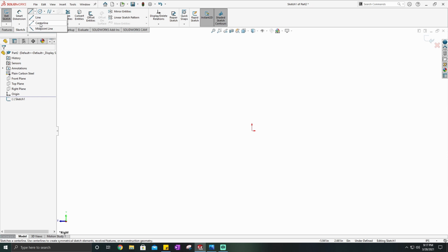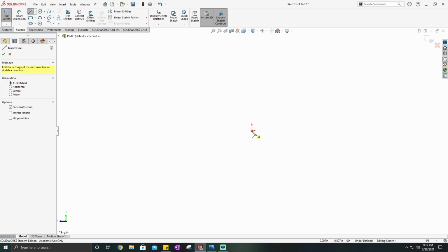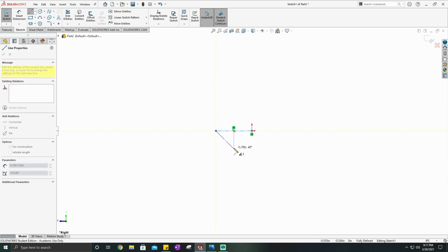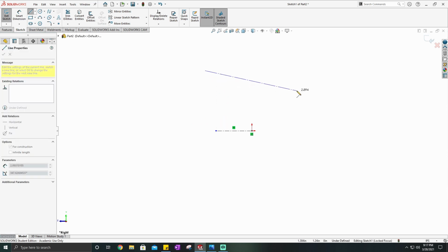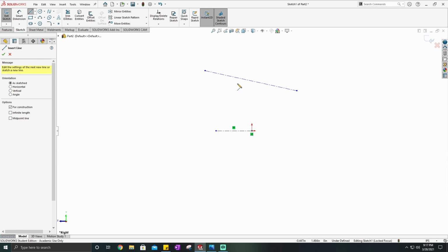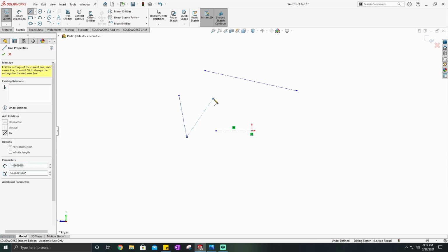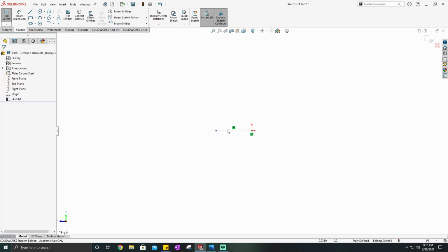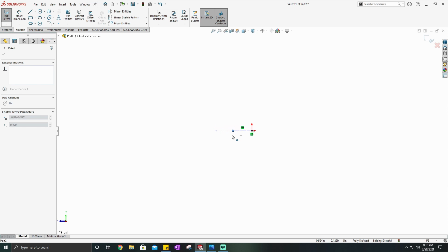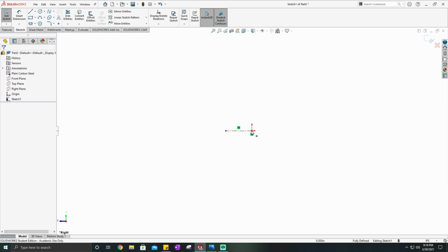The first thing to do is start where my axis of rotation is going to be. I want it to be right around the center, so I'm just going to go ahead and center line from here out to the side and double click. That's a little thing. If you're in a line tool and you want to place a line, you can just click to place a line, place it somewhere, and then it likes to have you place another one. But if you don't want to do that and you don't want to press the escape key, you can just double click really fast and it'll get you out of it, and you can go ahead and place another line somewhere else. I don't need these lines, so I'm just going to go ahead and get rid of those really fast. But yes, the length doesn't really matter on this, as long as it's just a line that you're going to revolve around and that it's straight, and I just have it lined up in the center.